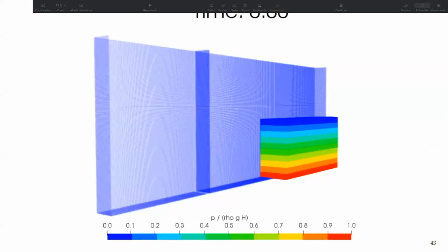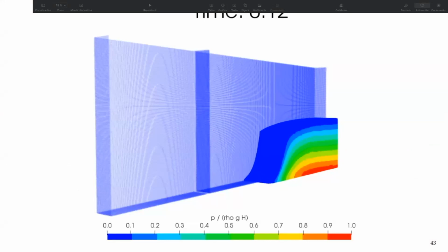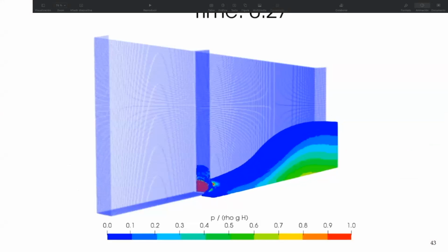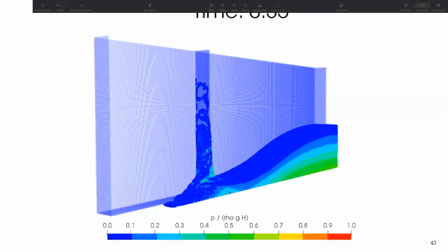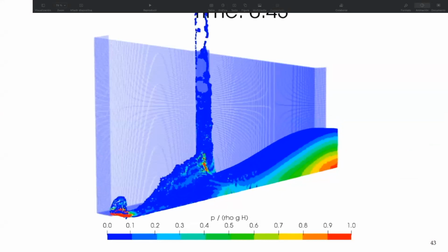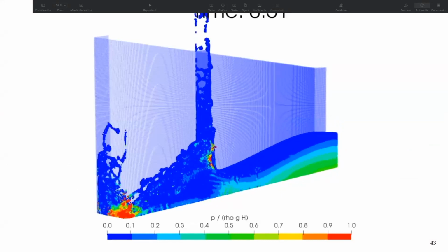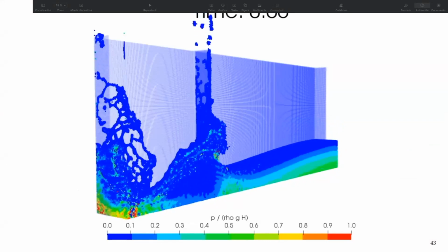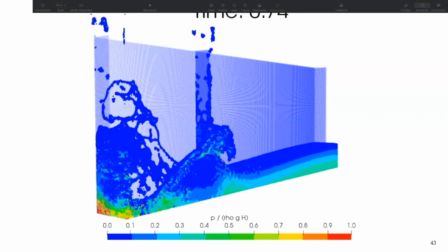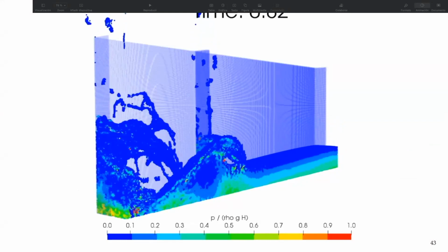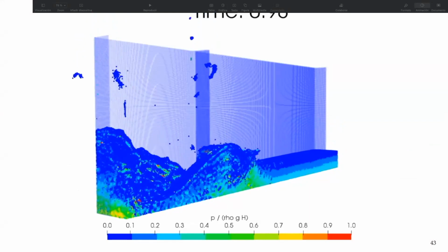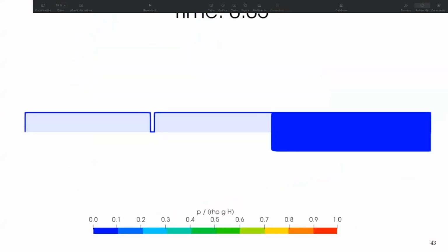Now here we can see a video of a numerical simulation of this same 3-dimensional dam break test. We have considered different kernels, including the 3 well-known kernels and also the cubic spline. And the boundary integral technique is used to deal with boundary conditions. In particular, the formulation presented by Calderon and collaborators in 2009 is used. In that formulation, a kind of potential of the kernel is defined in order to be able to compute the Shepard factor close to the boundaries.